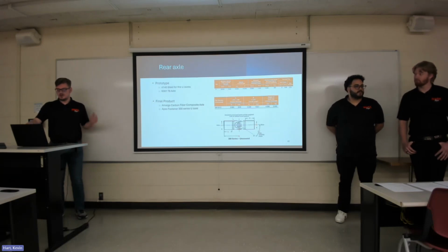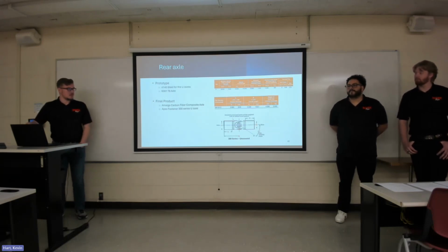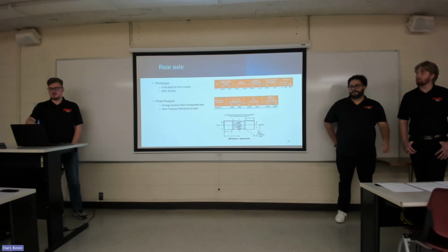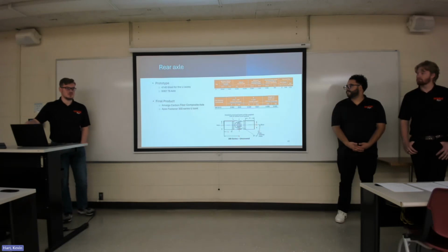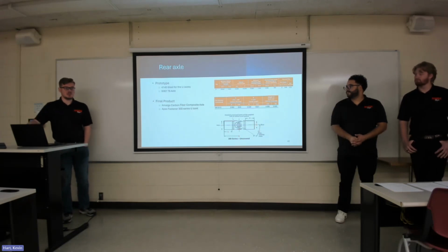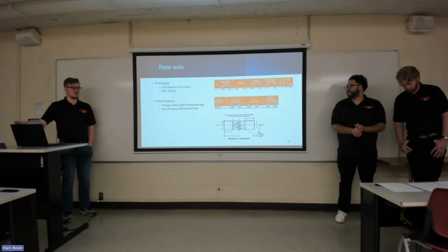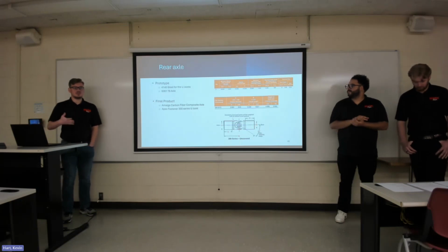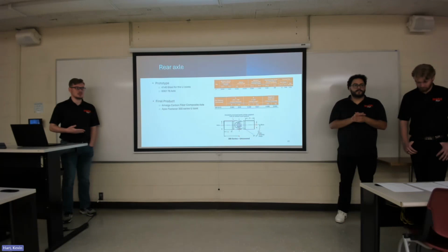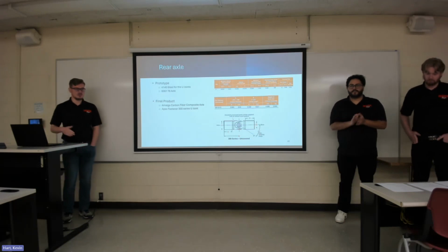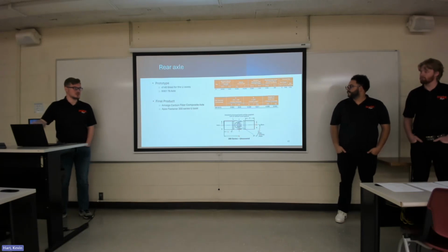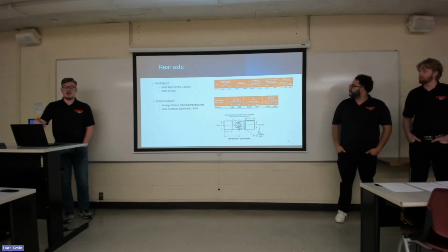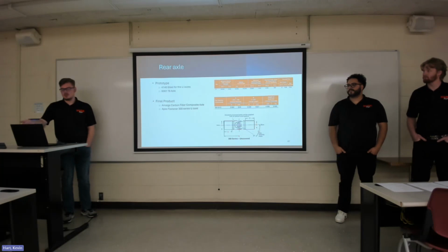So the prototype of the rear axles will be using 4140 steel for the U-joints. Ideally, we hope to reach out to the previously mentioned research supplier known as Apex Fastener to hopefully get at least 2 U-joints, so then we can do some testing and understand how they will react to certain loads. But if we have to, at least we'll know what steel to use to machine them ourselves. The physical tubing we'll be using for the axle is going to be 6061 aluminum, because that's just everywhere in our shop.